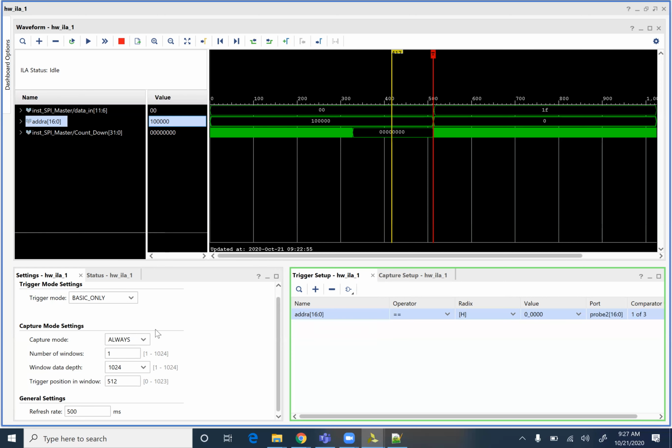So you'll just switch which side of the equation the input or output goes on, and the synthesis will take care of it. As long as you don't try to read and write inside the same case within a case statement. But we won't, because we're going to have transmit and receive states, which are going to do different things. It should take care of that for us. If not, we'll figure it out.